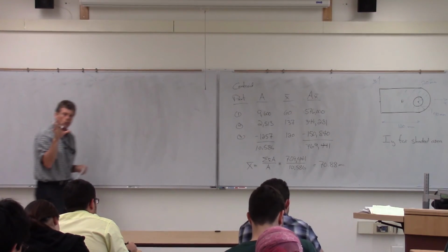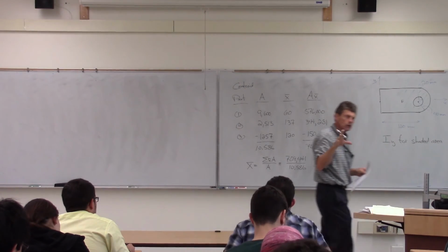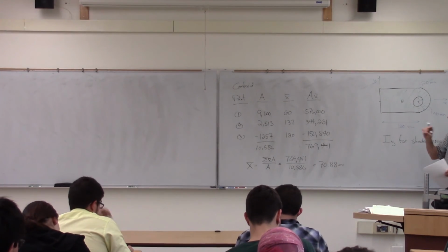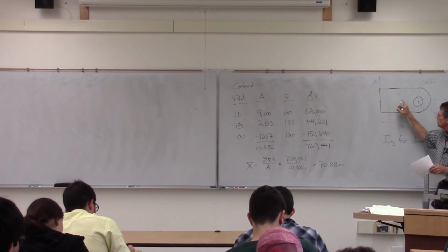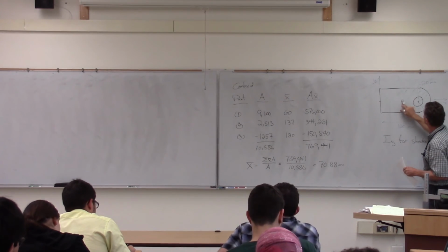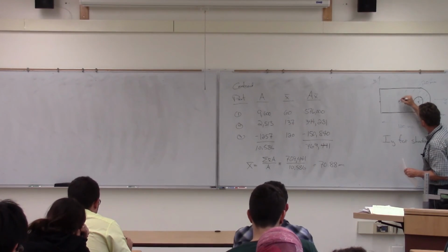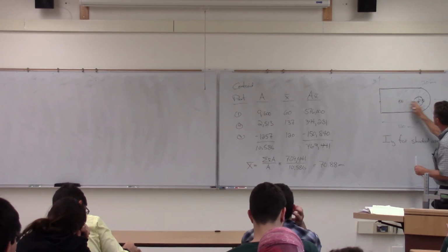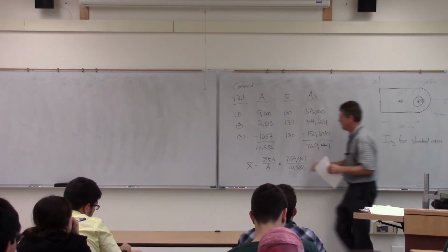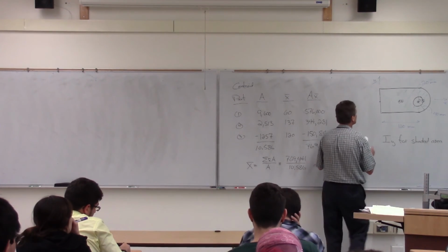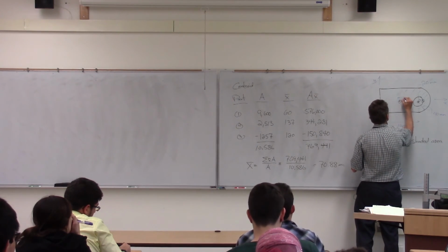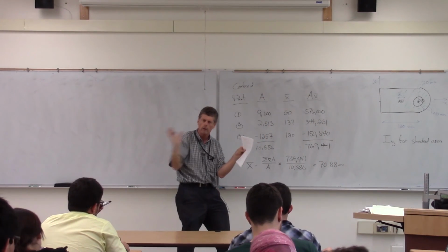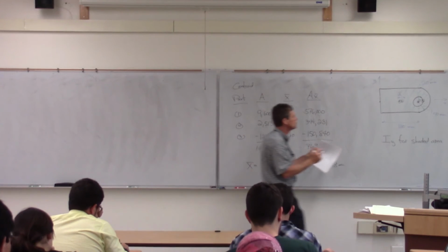Then the key thing is I'm going to reconstruct this through the parallel axis theorem, but I'm now going to use these new d's. I need to calculate a d. I've got the centroid of this section, but now I have to measure to the centroid of the box section, the centroid of the circle, and then the centroid of that. So my distances now, we'll call that d1 prime. That's the distance from the centroid of the entire section to the centroid of that rectangular section.